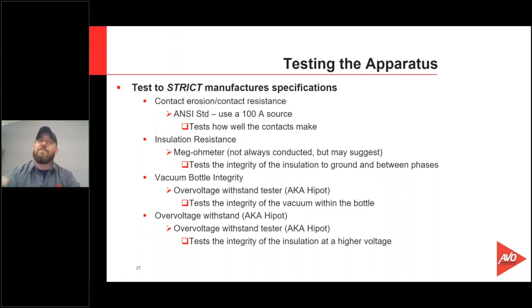Okay, I get it. And then, of course, at the very last page, on the very bottom, they're going to give you about an inch and a half worth of line, and it's going to say, in case you don't have an AC tester, use a DC tester. So that's where the square root of 2 comes into play when it comes to converting an AC test to a DC test. So use the square root of 2 to come up with the proper DC test voltage when it comes to an AC test voltage that's been supplied by the manufacturer.